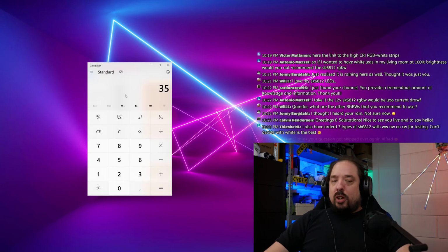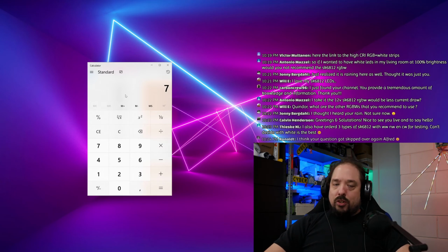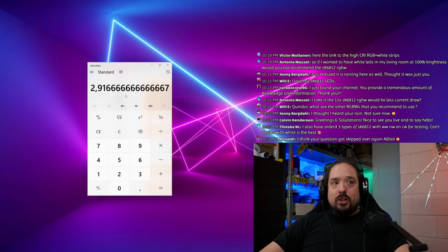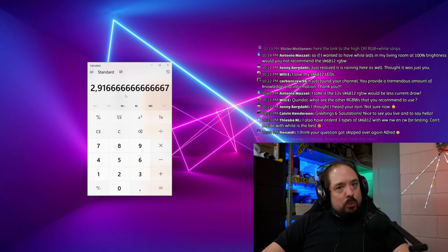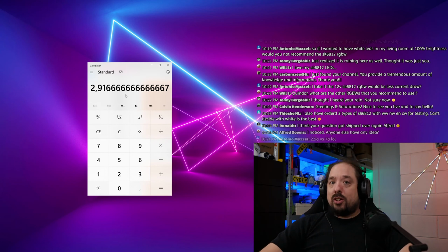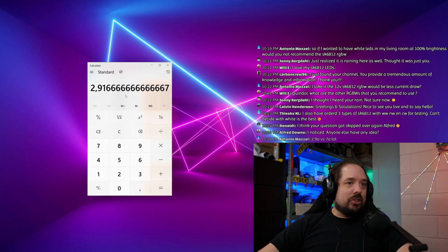Awesome. So if we're talking 5 volts and 35 watt, that's 7 amps. But if we're talking 35 watts at 12 volt, that's only 2.91 amps. So what that basically means is that your cabling will be a lot easier because you need a lot less copper because of the higher voltage. Does that answer your question?